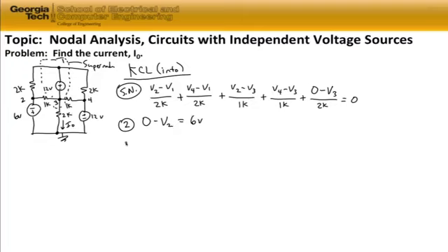We have an equation for node 4. I'm going to call that the node 4 equation. In a similar fashion, we can find the nodal voltage for node 4 directly from our circuit. In this case, it's V4, which is tied to the positive polarity of the 12-volt source, minus the reference voltage at ground, 0 volts, is equal to 12 volts.